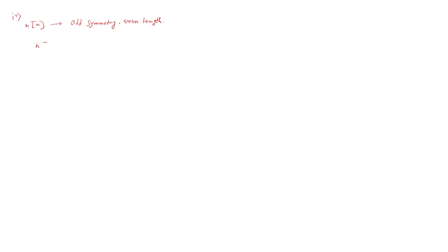Therefore you can write its impulse response like that. Let us consider the length to be 4, so the first and last components should differ in sign. The second and second last show the same behavior. So your impulse response can be drawn like this.